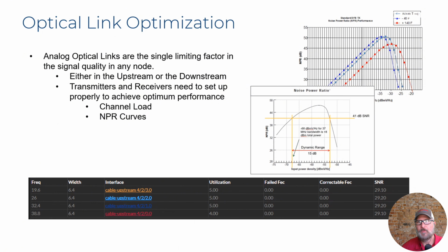And so we spent a lot of time early on, when we had these really large nodes with a lot less data, that we had to manage for noise, because there were so many devices connected in a single upstream analog optical path that we wanted to avoid the laser clipping. We didn't want to take all of that funneled and combined noise and clip the laser.